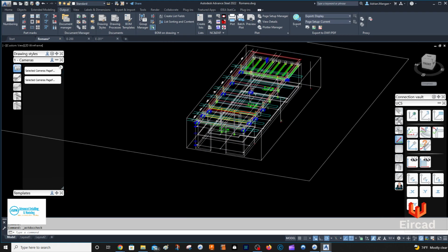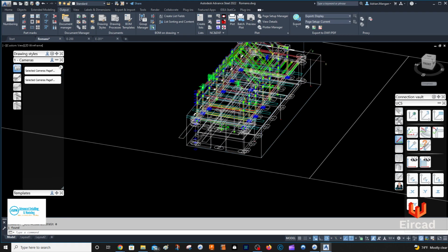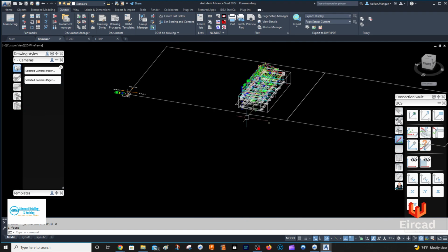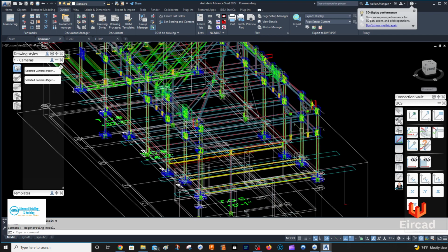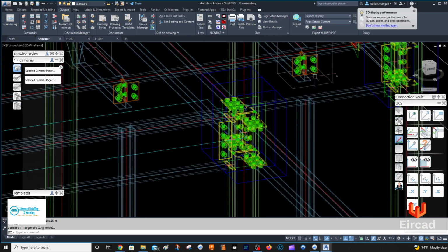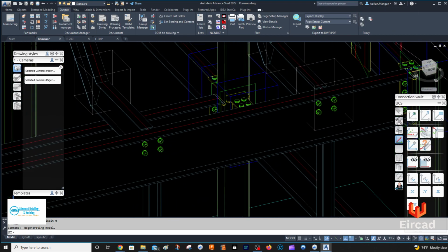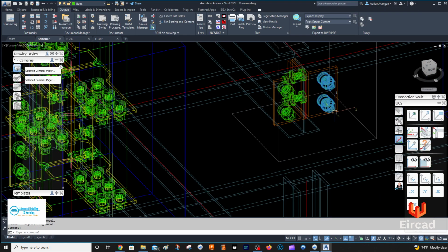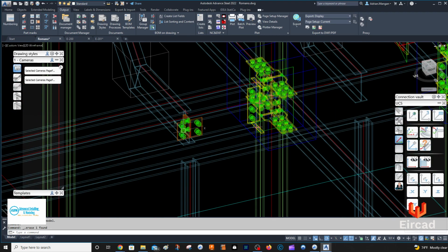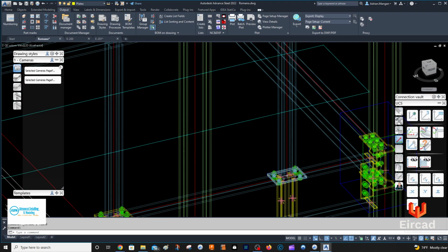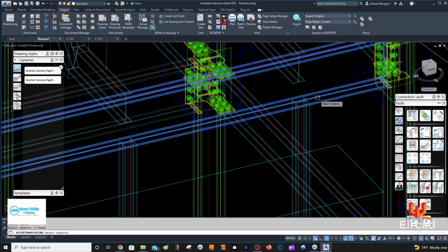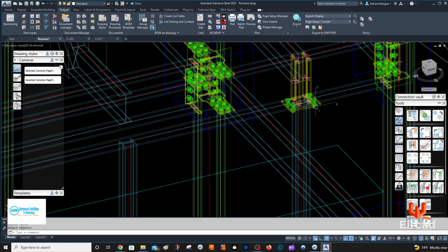So let me fix that first. So that is on this side, right? Yeah, so up here. So what we'll do is this connection is not going to fit. So let's delete this. We're going to delete these two connections. And then I'm just going to put the same connection that's on the bottom on the top, and I'm just going to copy it, not intelligently. And then this one I will copy intelligently, so it's connected to this one.